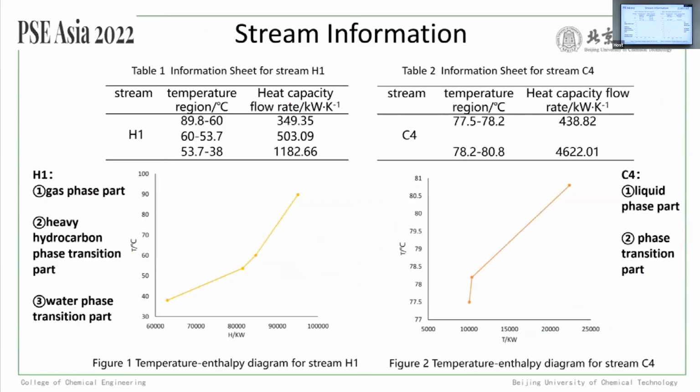To better describe the process in the heat exchange network, a pseudo stream is defined, which can be characterized by a constant heat capacity with component transferred from one phase to another in one stream, usually between gas and liquid phases. Six streams are considered in different temperature intervals according to their phase change characters. Taking each one stream as an example, it is a vapor-liquid coexistence phase after heat transfer.